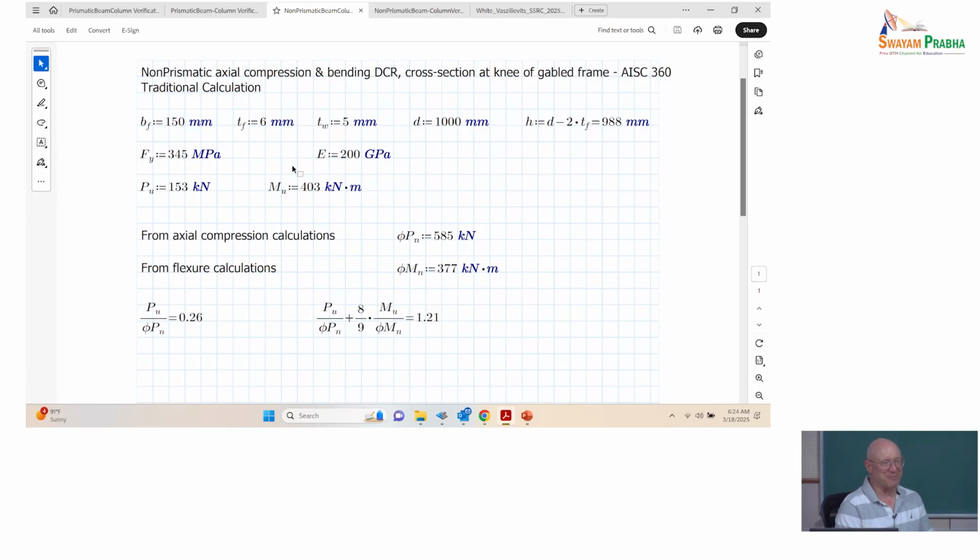So that ends up being a huge headache. Then we contorted ourselves all sorts of ways to address that question in Design Guide 25. So if you put on these notional loads, then you can take that bending out and now you've got pure axial compression, and oh my God.